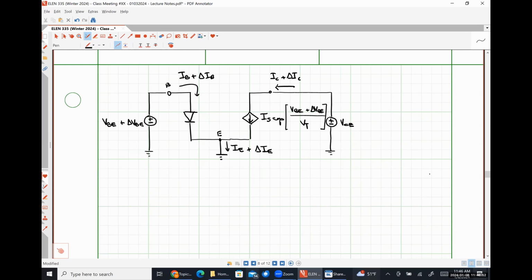Transconductance of BJT. All right, so transconductance is a measure of efficiency in a transistor device. It's effectively quantifying the device's ability to convert an input voltage into an output current. So effectively, how well this VBE here at the input of our device gets transformed into a collector current. And its value depends on the DC operating point of the circuit.